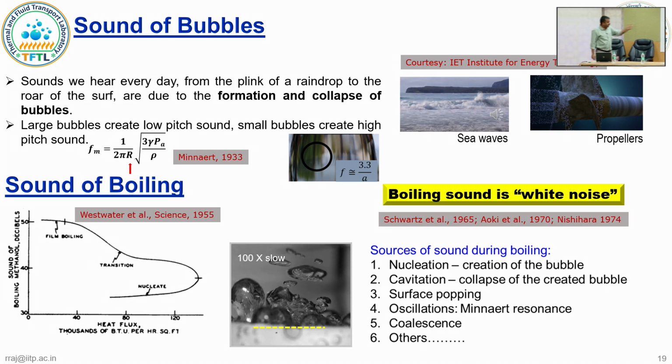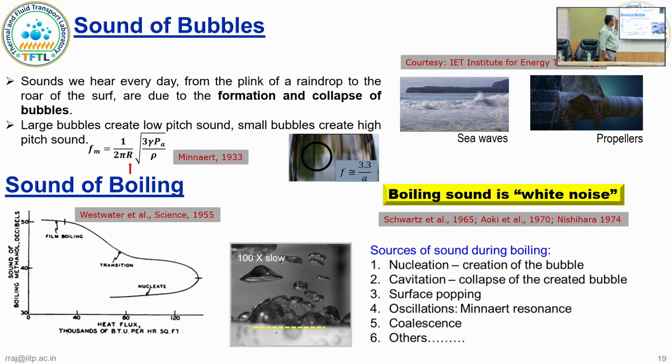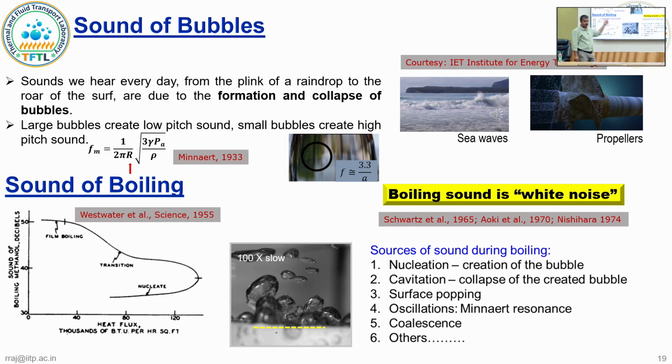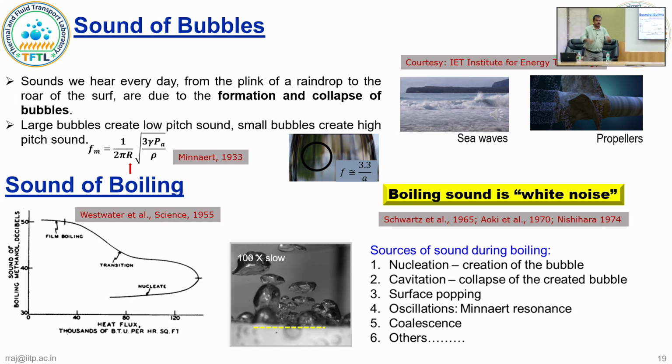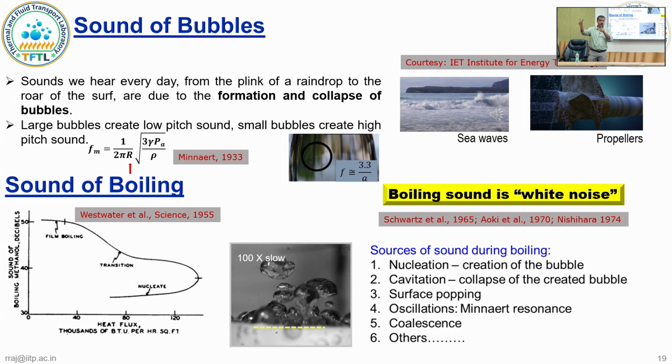And it is understood because boiling has so many sources for emitting sound. There's a nucleation process which gives you sound, if it's subcooled fluid, cavitation, surface popping, that gives you a sound. Oscillations of all of these bubbles gives you sound. And now you can imagine how complex it is.